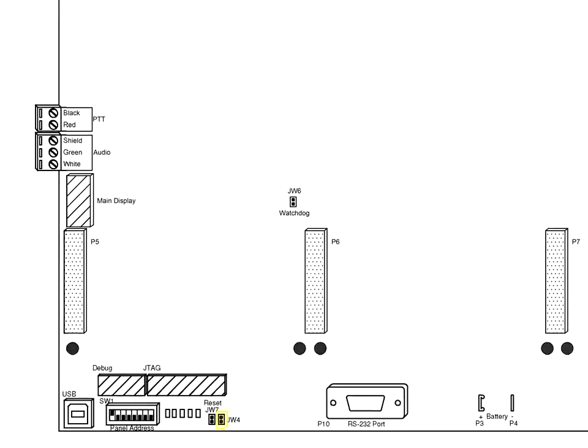JW4 is for factory use and is normally open. JW7 can be shorted momentarily if you wish to reset the panel. To the left of JW7 is a bank of troubleshooting LEDs that can be utilized in the field to troubleshoot any issues on the QX Mini Series panel.